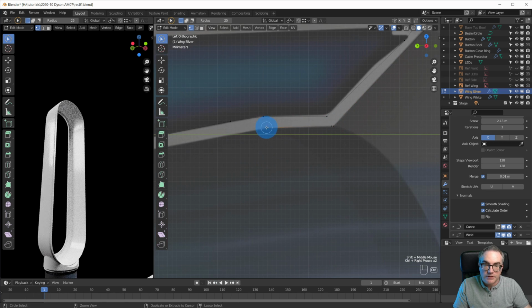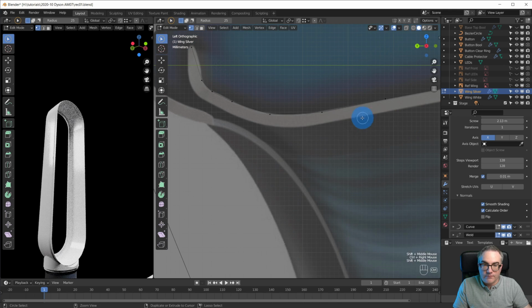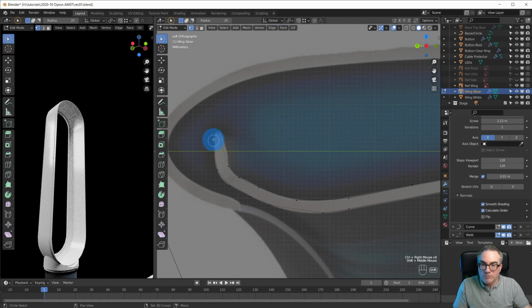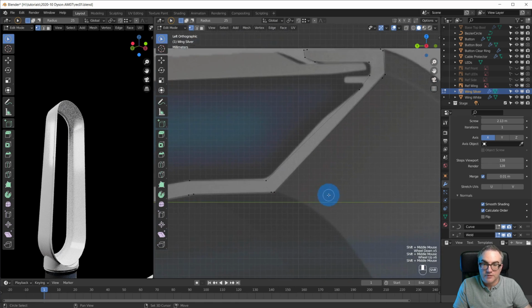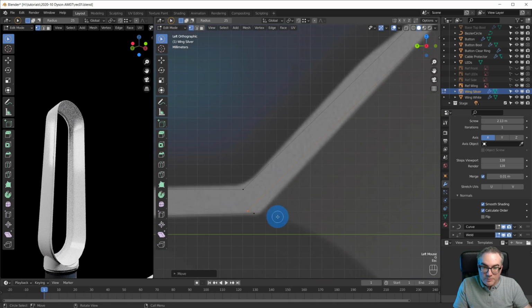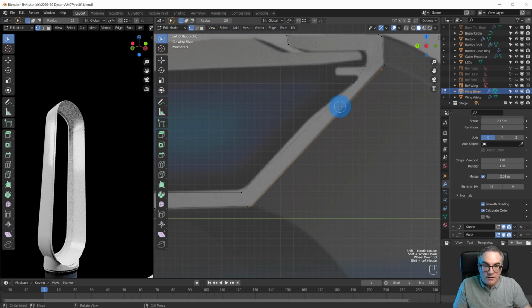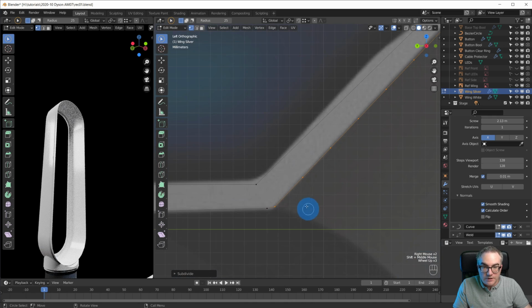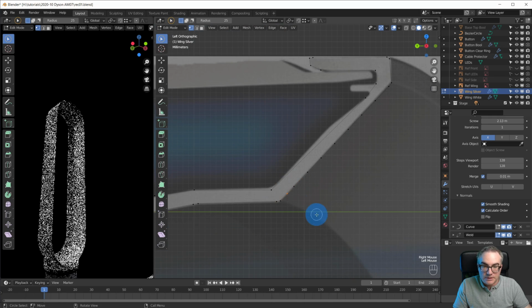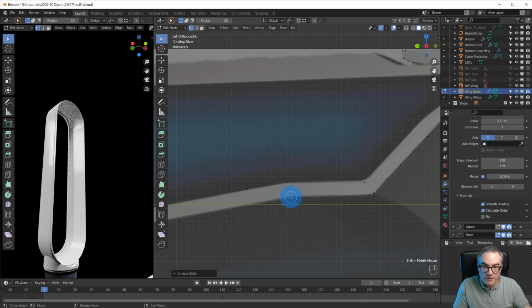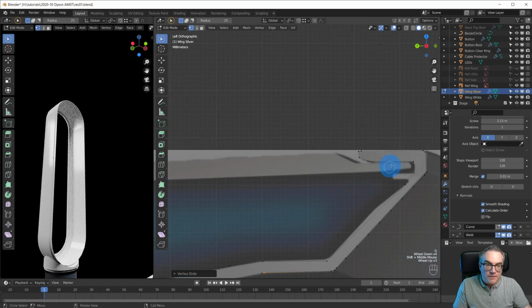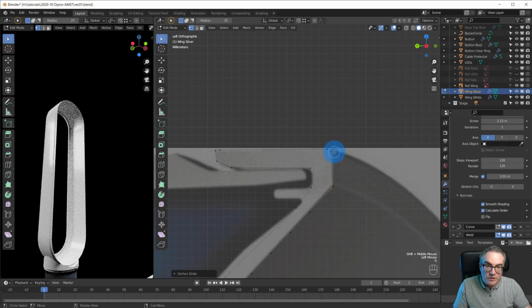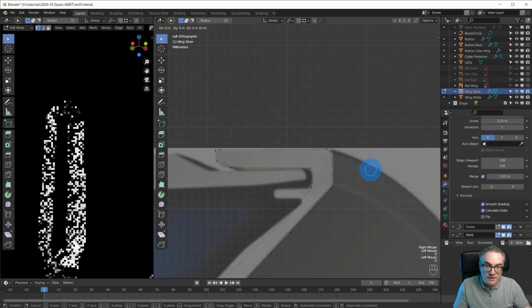And I want nice sharp edges here. And then this round piece, and then just F to finish this off. Now I'm going to move this around a little. Also subdivide here a few times to make this a very straight line. Subdivide these two and GG this one down here to get a sharper corner here. Like so. Also up here we need a very sharp edge, so we have to subdivide here and bring that in.